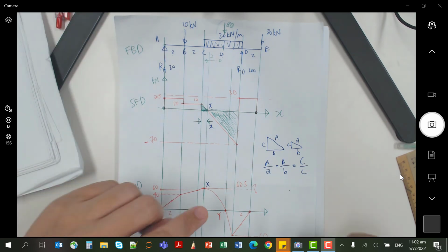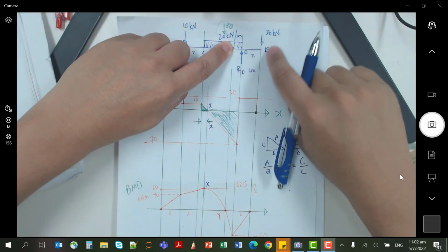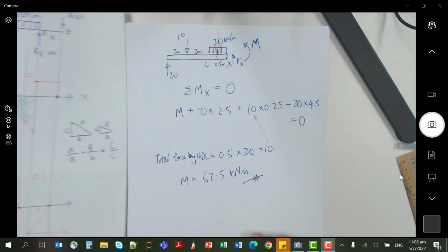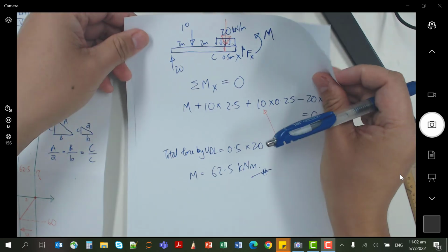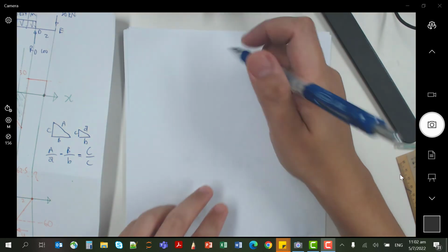When the forces are much simpler on the other side, the recommendation is to use the side with fewer forces. So let us cut at Y, since there are only these few forces, and we will balance out the forces and moments. So for this case, your free body diagram will look like this.